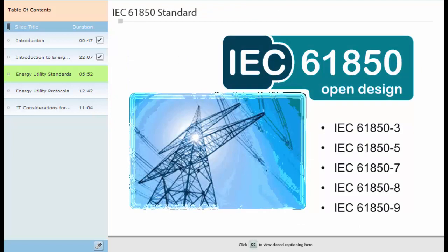IEC 61850 is a relatively new international standard for communications and systems within the substation. IEC 61850 is unique in that it is not an old serial link protocol recast onto TCP/IP Ethernet. IEC 61850 was originally designed to operate over modern networks and delivers new functionality that is not available from legacy substation protocols. IEC 61850 standard defines the requirement for substation automation.